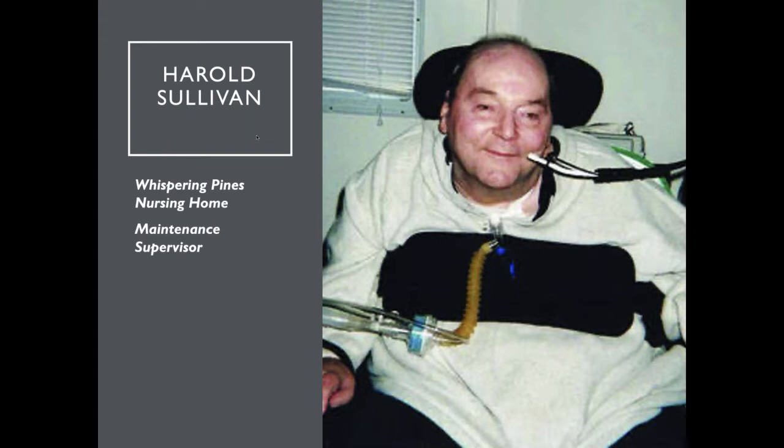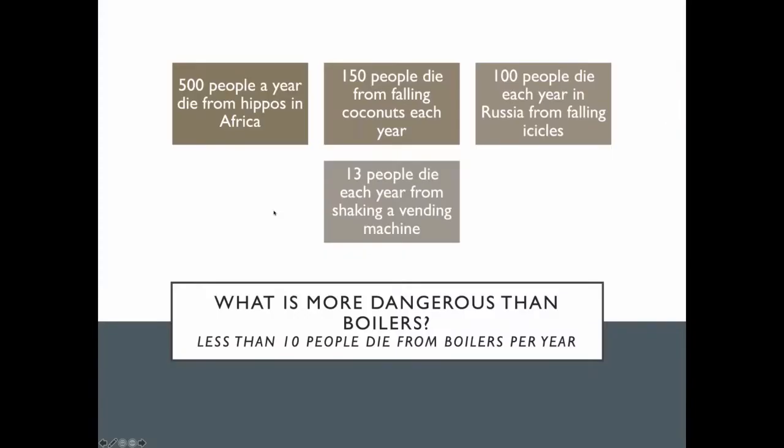And what I tell people when you're going out onto a job site and where you have a boiler, push the reset button once. If it fails again, you need to find a cause. You just can't keep pushing the reset button because you don't want to end up like Harold here.